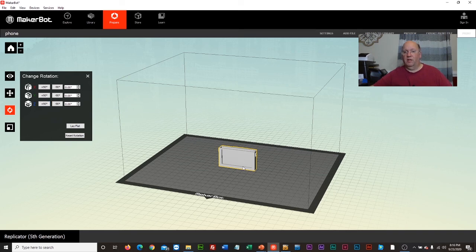Simply put, the printer prints from bottom to top. If there's some critical surface on the bottom, you may want to flip it. You may want the critical stuff to be on top because it doesn't have to have the entire weight of the model on it. If there's a lot of details there, that may look rough, because the bottom surface may look rougher than the rest of it. Same thing with the sides. It may be better to print it vertically instead of horizontally.